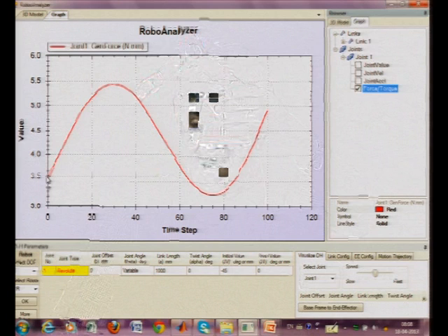So, I choose 6 axis, and you will see the KUKA robot coming up here. I take the isometric view, and here all the joints have been specified to go from 0 to 60 degrees. I perform forward kinematics and you can see its motion like that, and then you can perform inverse dynamics. So, this is inverse dynamics, and then you can look at the plots.